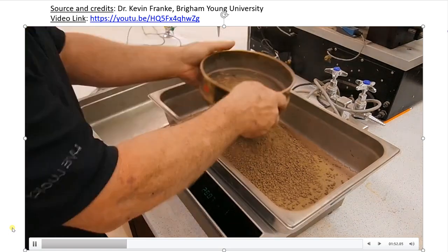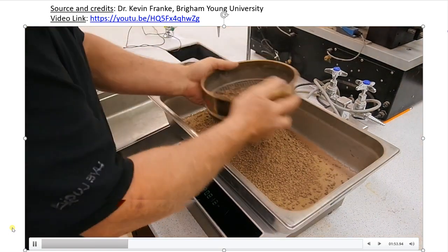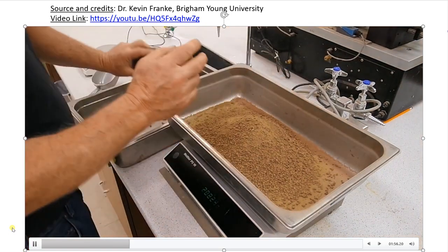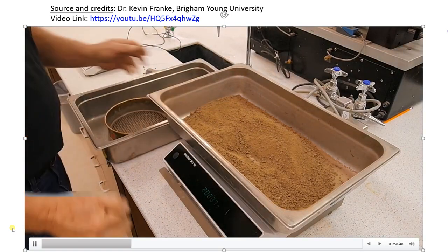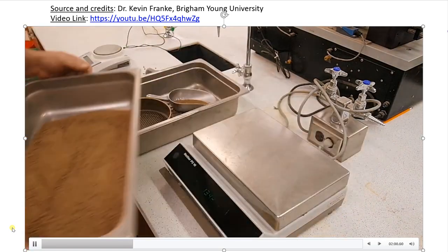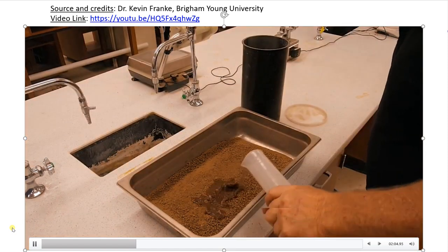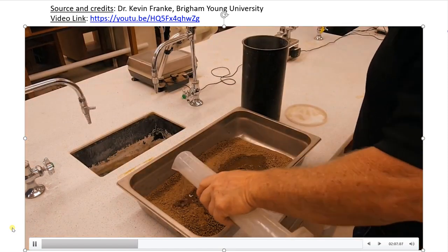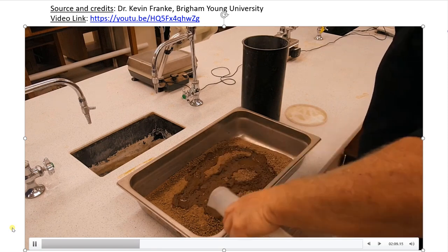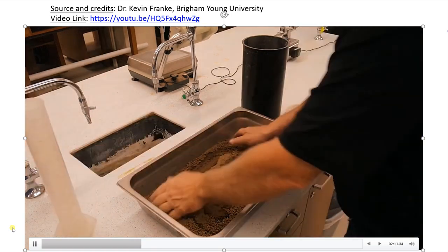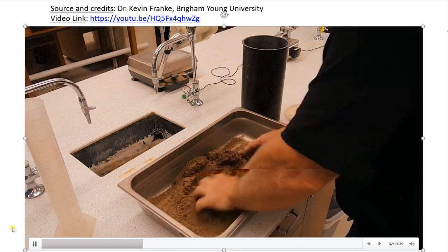Seeing how our samples have a significant amount of silts and clays, we will need to soak it for at least 12 hours. Once we have the material screened and separated into 4 samples, we will need to moisture condition the material. To do this, we need to know what the current moisture of the sample is and add the difference of that and the moisture content we want.